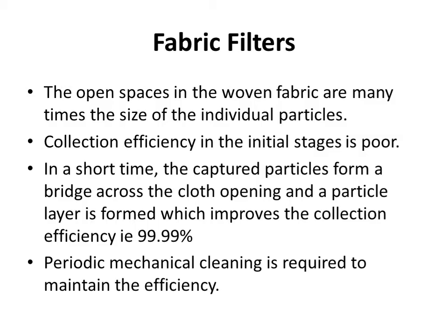Fabric filters are the most commonly used filters in industries. In this, the open spaces in the woven fabric are many times the size of the individual particles. The collection efficiency in the initial stages will be poor, but in a short time, the captured particles themselves form a bridge across the cloth opening and a particle layer is formed, which improves the collection efficiency up to 99.99%. Periodic mechanical cleaning is required to maintain the efficiency.